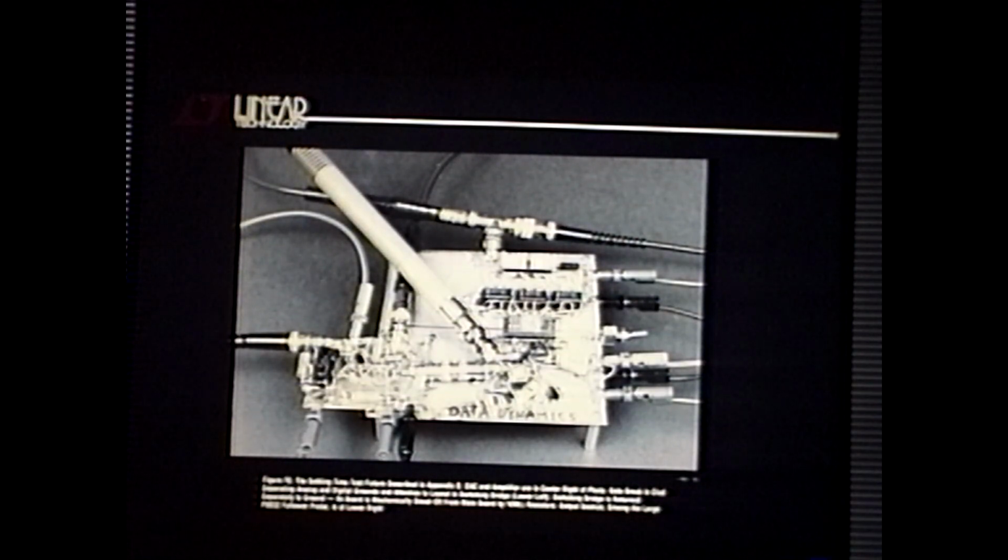Second, my sampling bridge that I built and the switch drive and everything else is built on a separate board which is grounded back at the power plane. I don't want the DAC currents and the bridge currents mixing either. Built on a separate board, the clad's not soldered here for common ground. I do the grounding at the point of measurement.